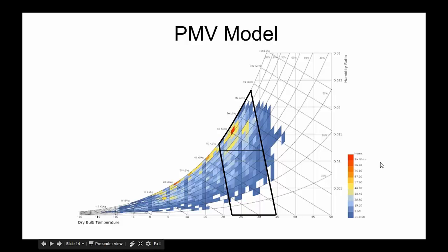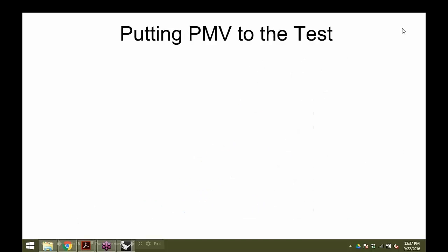So, all right, so we have one PMV model, and once this was produced, a lot of engineers started using it. It was used to derive all the thermostat set points that we use in a lot of our public buildings. But once that came to be, immediately a bunch of scientists said, all right, well, that's great that we have all these climate chamber tests that validated the model. And it's great that we have a human energy balance here, but how do we know this really relates to what people actually feel in real buildings? I mean, we know it describes that climate chamber really well.